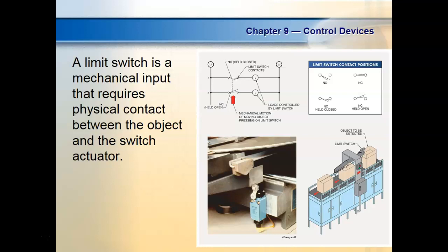This is an electromechanical device, which means what? It means it can fail two different ways. They can fail mechanically or they can fail electrically. The biggest problem we have is people don't seal them back up when they get in. It's got a gasket around it, so when you put the cover on, it seals it up.